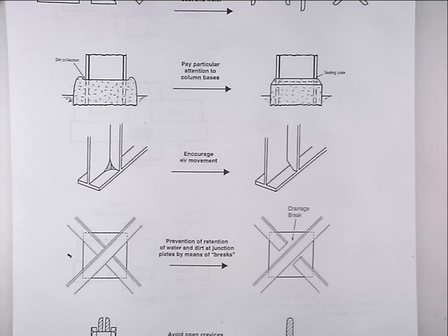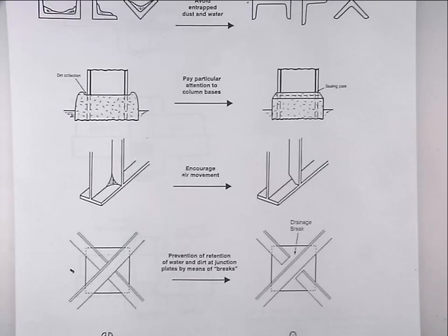So these are just some examples from civil engineering for drying out the environment. And again, you're breaking the electrical circuit. That's the basis of stopping the corrosion. If the anode and cathode don't have an electrical contact between them, if the electrolyte is missing, that's fine. Stops the attack.